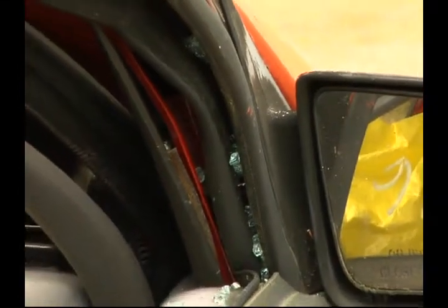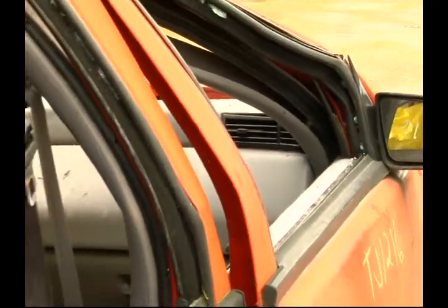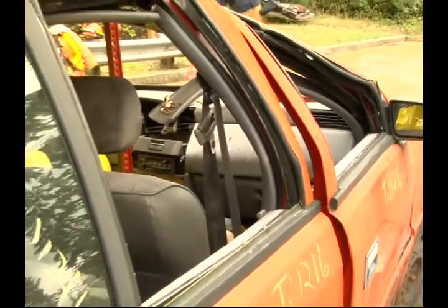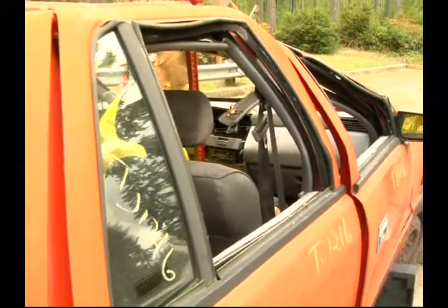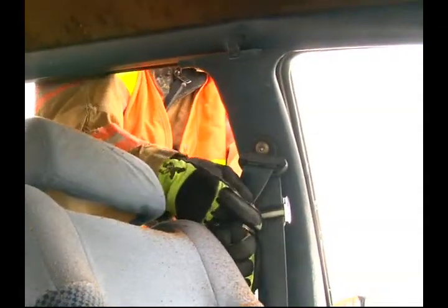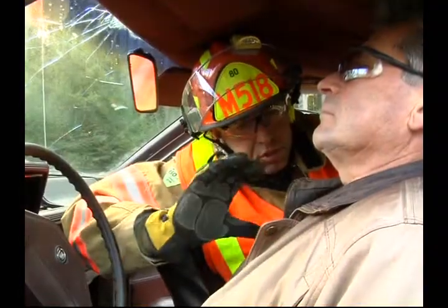When raising a roof, take advantage of already existing crash-inflicted damage when placing and operating your equipment. The area that has suffered the most damage will often be the easiest to bend back as well. As with any roof task, begin by cutting all the seat belts before starting the roof procedure. This will help prevent further injury to occupants trapped inside.